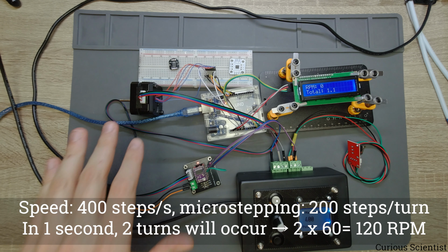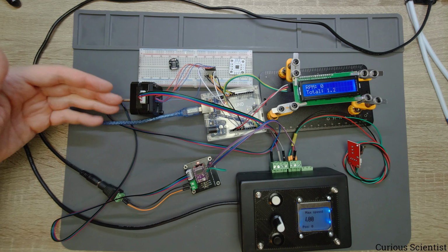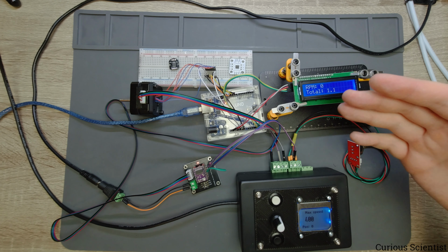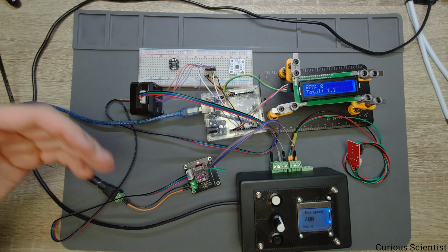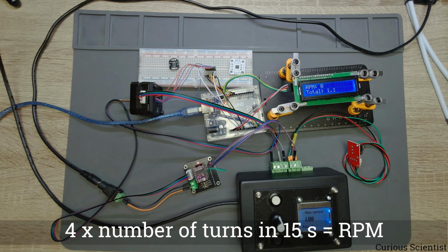And you will see it in the code how I calculate it, but we need to wait some time in order to get proper numbers here, because we have to accumulate a certain number of turns to get proper statistics, and then we can calculate the RPM. Basically, I'm collecting the number of turns for 15 seconds, and then that is extrapolated to 1 minute. I just multiply the number of turns by 4, and that's all.